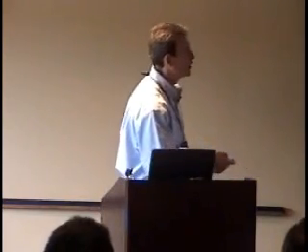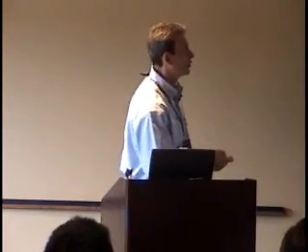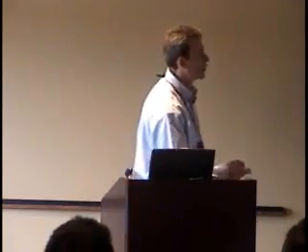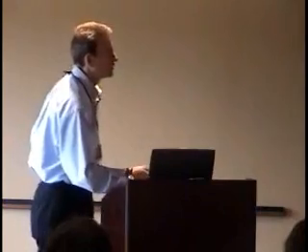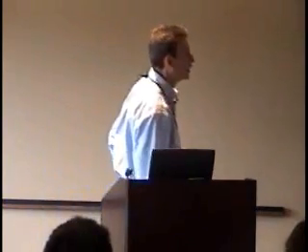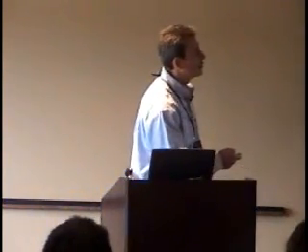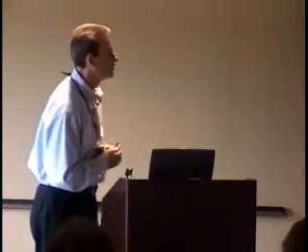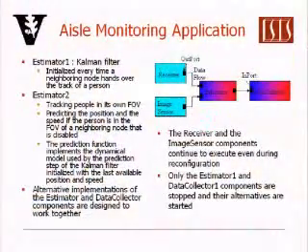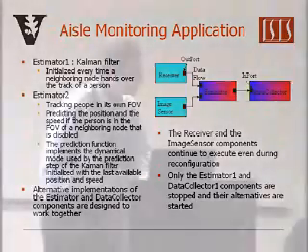What we do is one-dimensional tracking of people walking in the hallway. We have different software components, for example, motion detection to initialize the tracking, using Kalman filtering, data recording, and communication. We may have multiple people walking, but we are going to assume that there is only one person per field of view in order to simplify a bit the signal processing. And the sampling frequency was set to 4 frames per second. That is fast enough for tracking people walking.